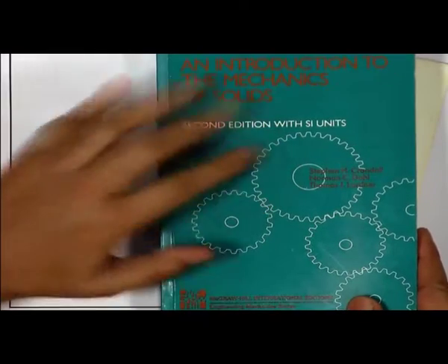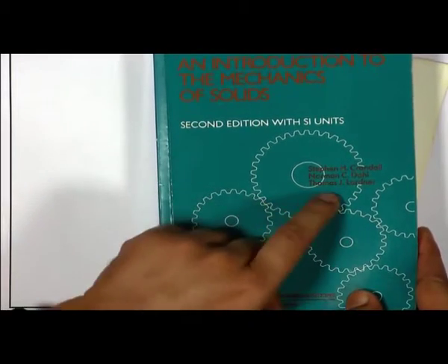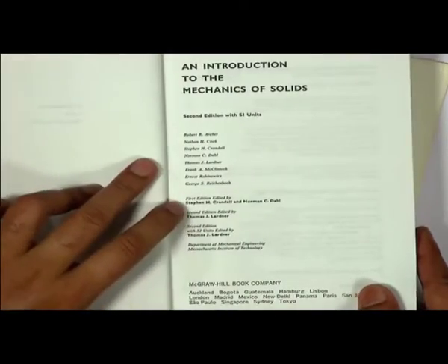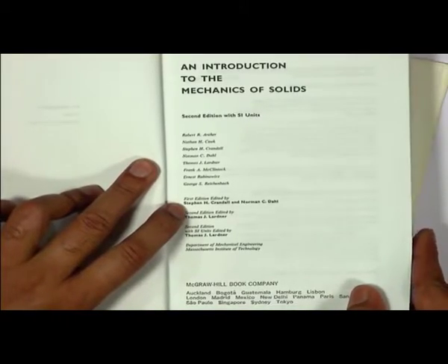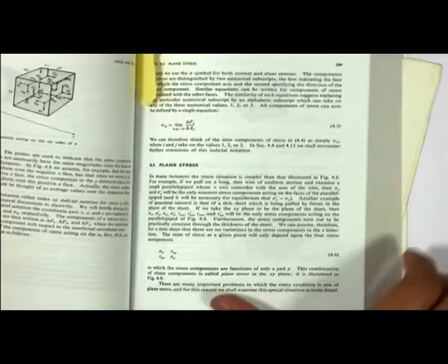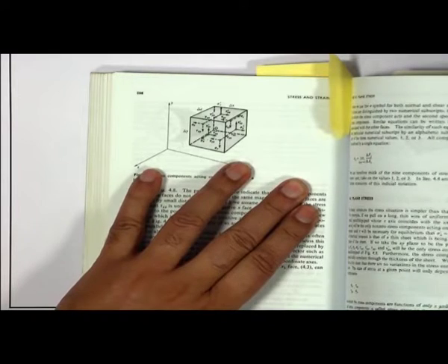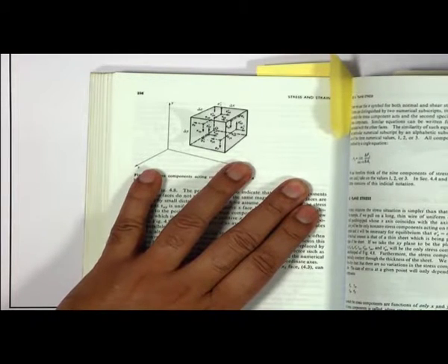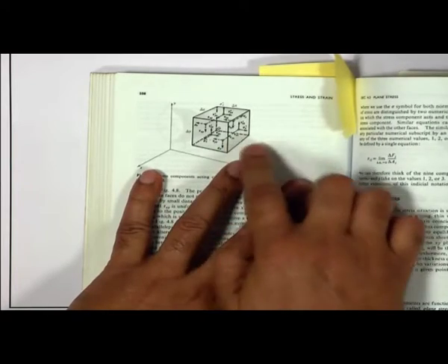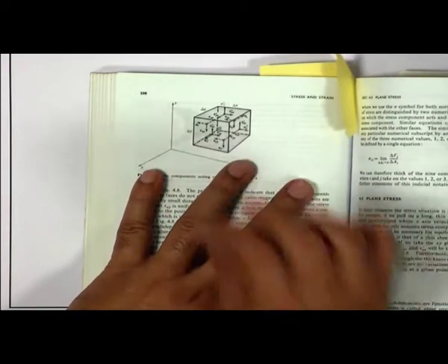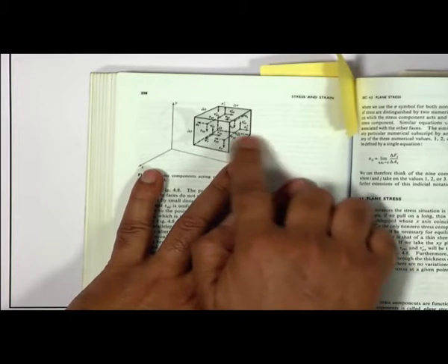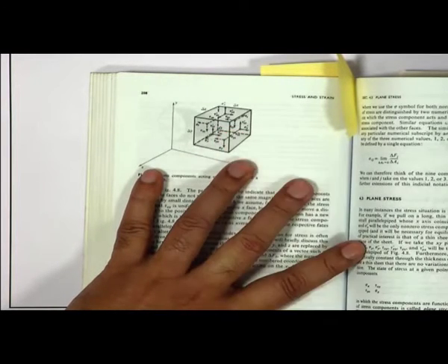Now, for that, you can focus here, I have taken one textbook. It is an old textbook, but it is very nicely explained, by Professor Crandall, Dahl and Lardner. Here are the names of the professors, so you can look later if you get an opportunity. But we will show you a diagram here. You see, when the stresses are three-dimensional in a body, how do we represent the state of stress? Suppose this is a cuboid inside a body. One is the normal force, another is the shearing force, which will have two components here.